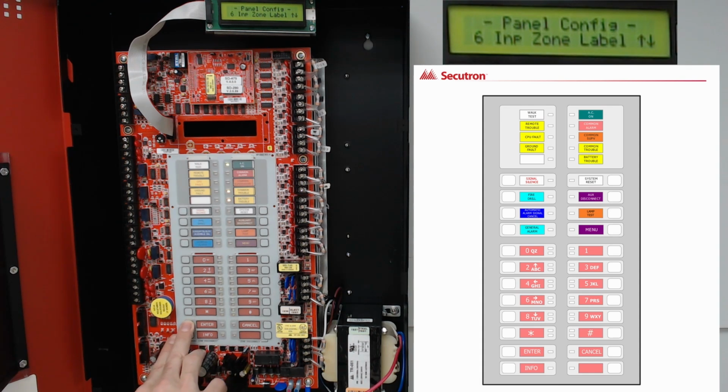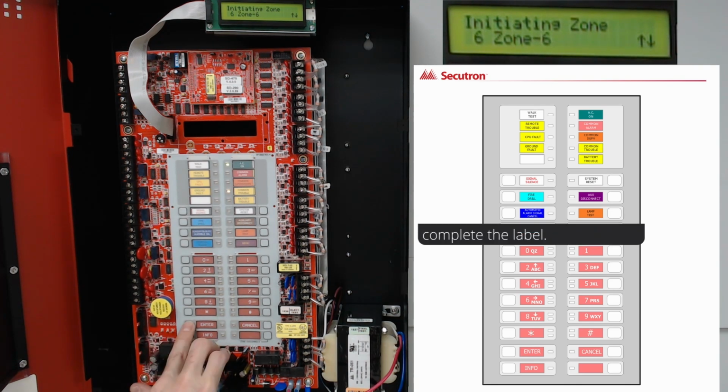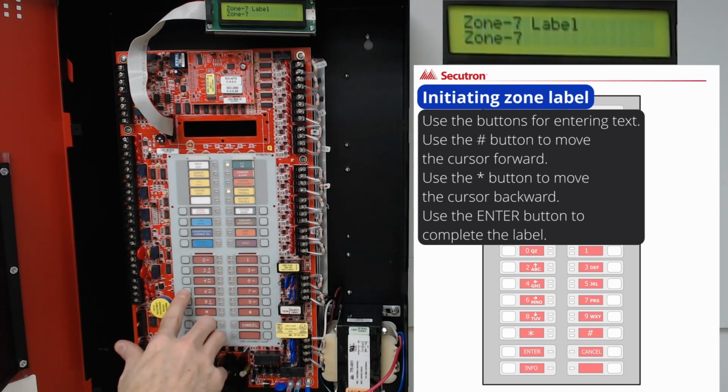By pressing enter, we'll enter in and see our 12 initiating zones. By pressing the up or down cursor arrows, we can find the zone we choose to label. When we find the zone that we want to label, we'll hit enter and go into the label screen. From here, we'll have to hit the buttons to get the desired text.